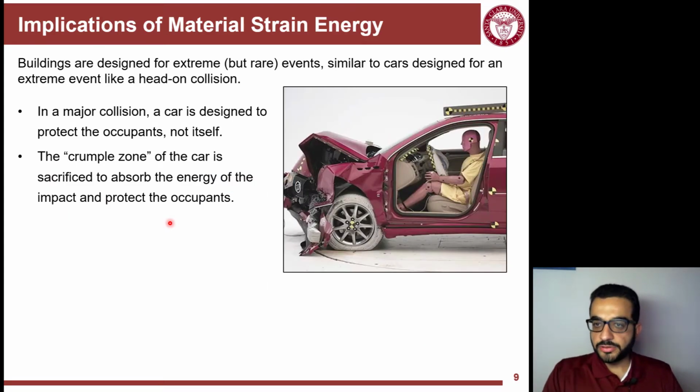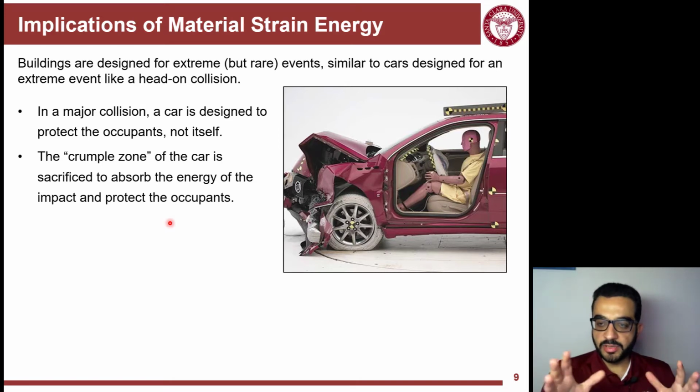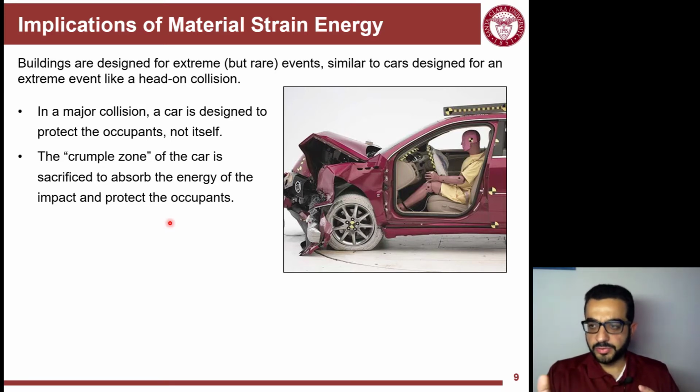Another thing to think about, for mechanical engineers, is designing a car. We always feel bad when you have a car accident and a collision in the front, destroying the front of the car. It is actually designed on purpose to do that. We could have made the car tough or a little elastic, but this energy, if it does not cause damage to the car, goes where? It goes to the rider, the driver. So for the safety of the driver, we are channeling the energy of the shock or the collision into the body of the car, into the front part, up to the limit that still keeps the driver safe. So there are a lot of applications of energy input into deforming materials, and they have a lot of impact on the safety of the structures or systems we design.